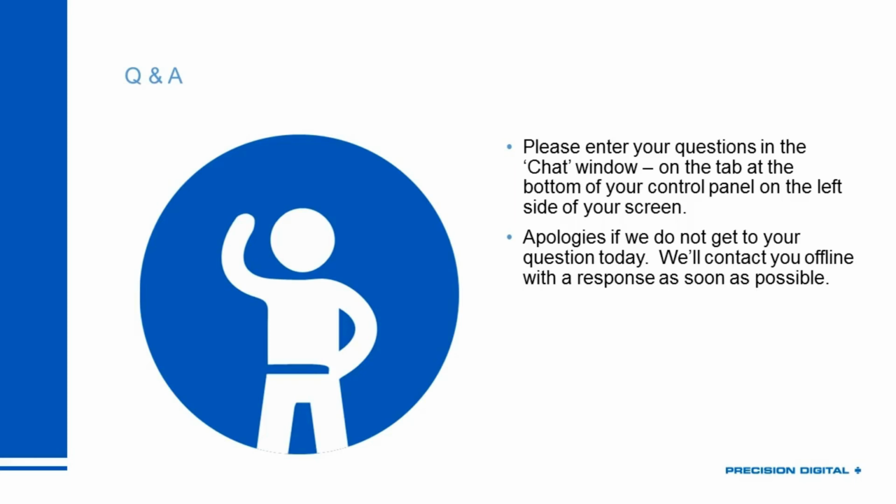I would generally say that whatever your power supply is rated for, so let's say you have a 24 volt supply, you want to keep a 10 to 15% limit on how much space you give yourself between what your voltage drops add up to be and your power supply is. So if I have a 24 volt power supply, I'm going to try to give myself 3 or 4 volts of headway just to make sure I don't run into a problem once I start loading this down.